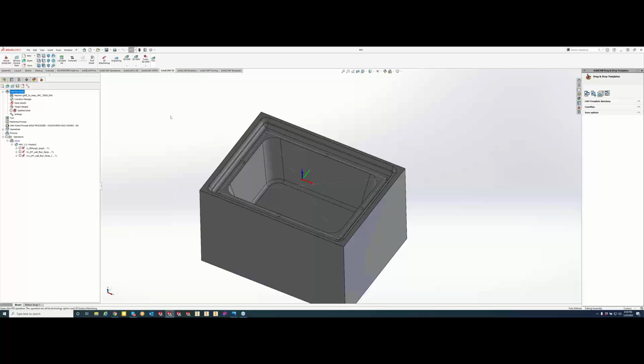All right. So what I am looking for, and I like to think of HSS, is you really want that perfect surface finish in there. You're going to want to use HSS. HSM will do a great job, but you won't get as nice of a job with HSS based off of the surface NURBS versus HSM using a faceted model.